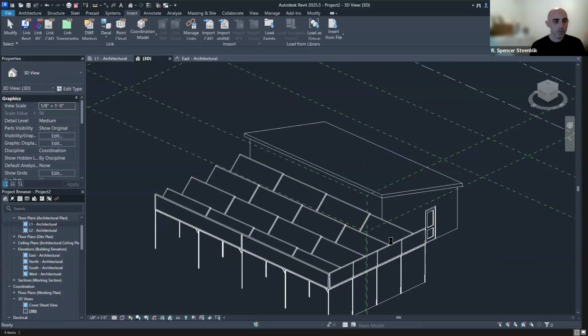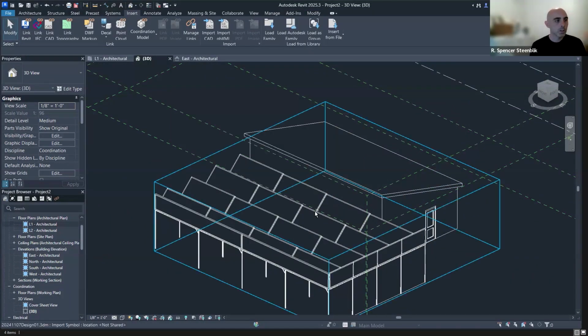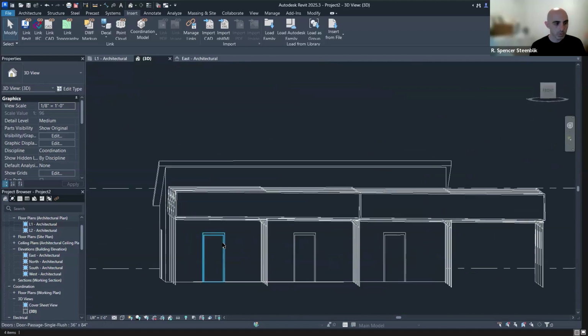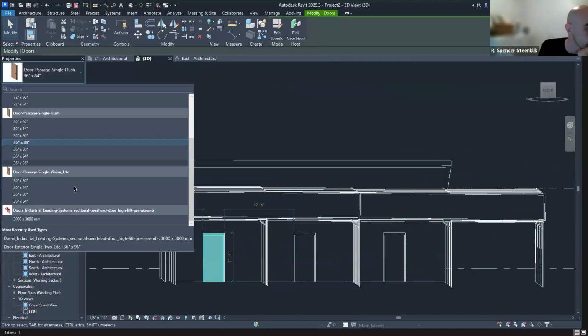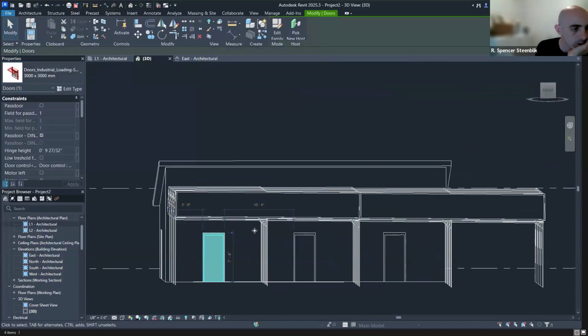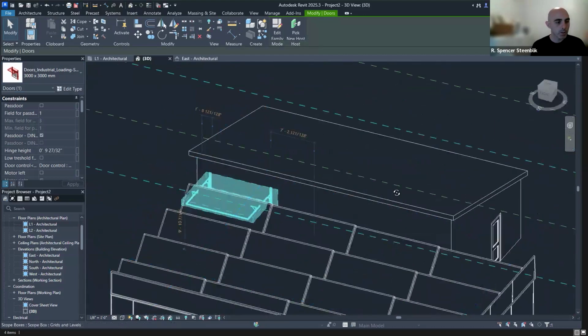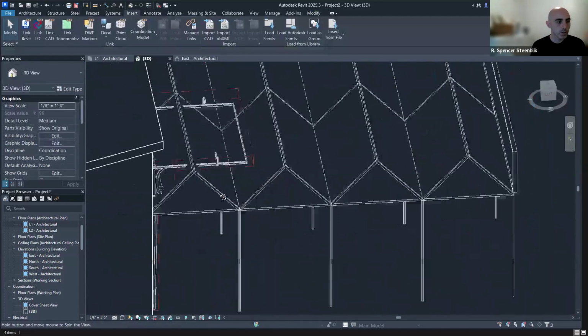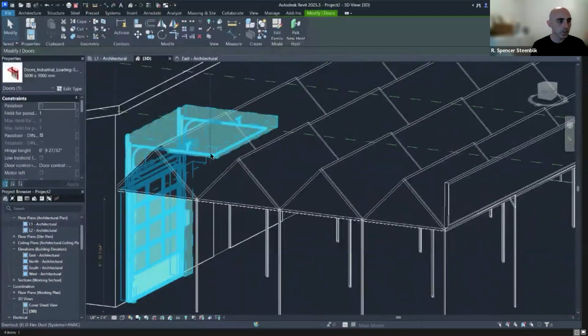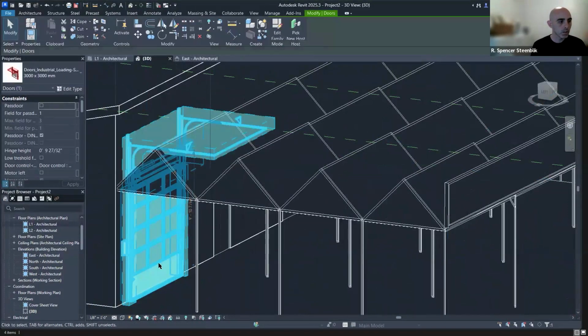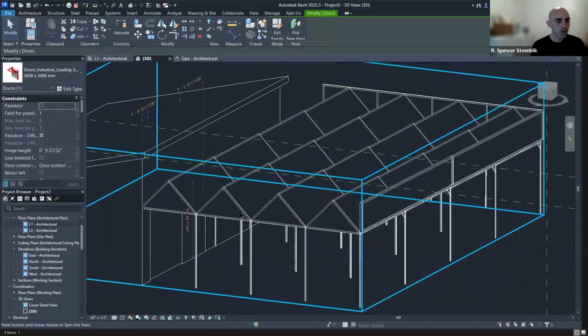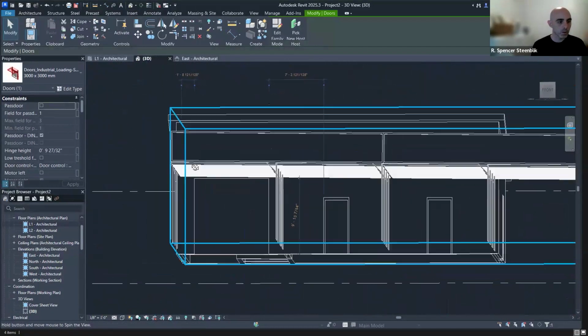While that's doing that, let's just talk about, okay, so it's loaded now. We should be able to adjust those to be that other family. Yeah, here we go. So there it is right there. And we want to flip that. You see how it's this other direction? It wants to be the other direction. If you just tap spacebar, it actually flips the orientation.